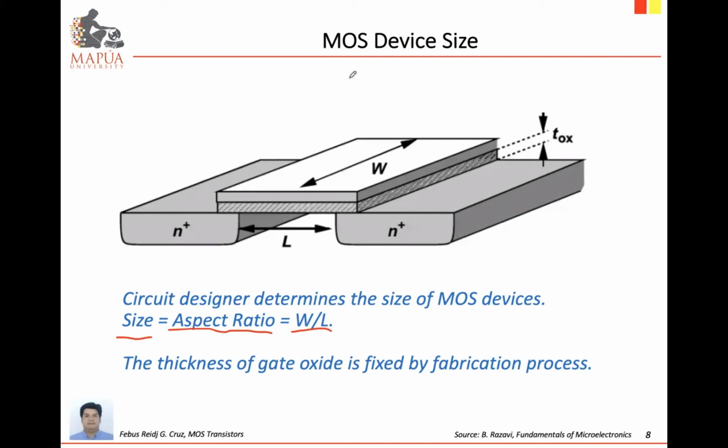So let's say, given a transistor size of 10, that means the transistor width will be 10 times larger compared to the transistor length. For this particular example, perhaps the device size is around 1.5. Based on this, we can see that the transistor width is approximately 1.5 times larger compared to the transistor length. All right, so again, transistor size pertains to the ratio of width over length.